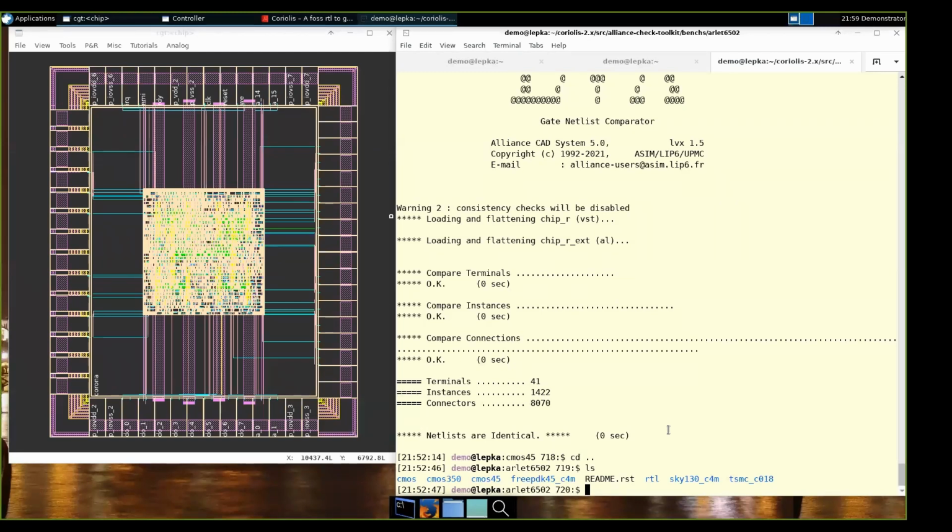One was for the PLL and one was for the SRAM, so that I could place those fake cells under the FreePDK45 without having to know about the NDA cell or the sizes or any information about them at all, except for what the inputs and the outputs were to the block at the overall level.